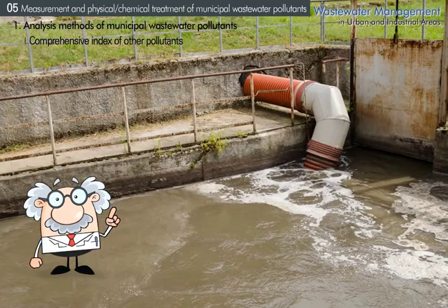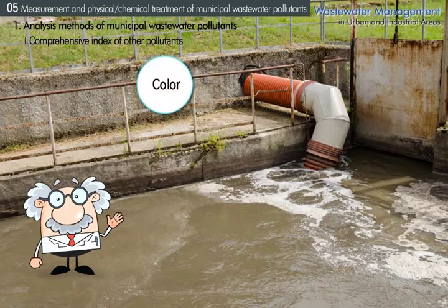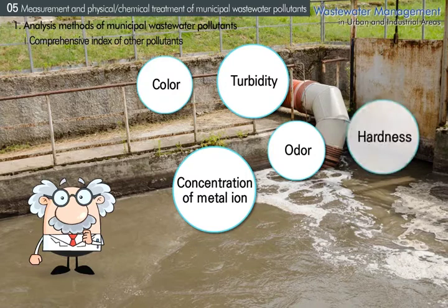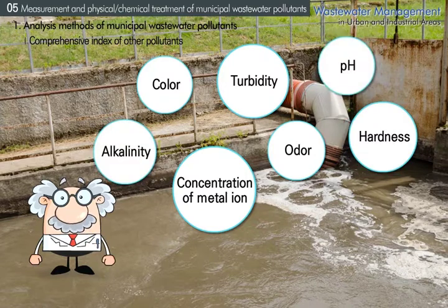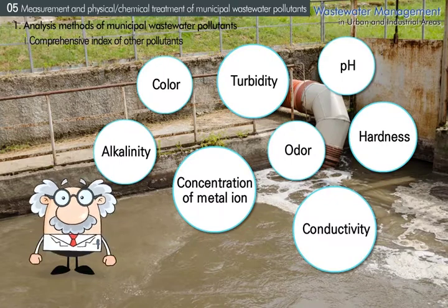Furthermore, to identify the amount and characteristics of pollutants in wastewater, color, turbidity, odor, metal ion concentration, hardness, alkalinity, hydrogen ion concentration, conductivity, etc. are measured.